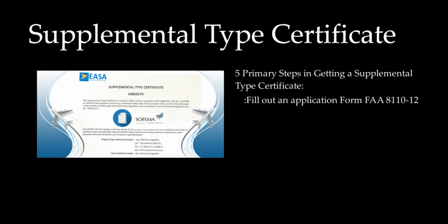Once the FAA opens your project, you must provide a detailed test and computations plan, according to FAR Part 21, Aircraft Certification. This plan requires developing engineering design data and showing the FAA how you plan to modify your aircraft. You are responsible for demonstrating that the changed product will comply with applicable regulations and airworthiness standards.